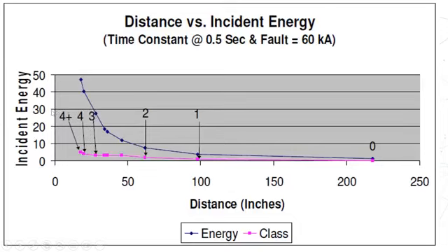Without knowing the incident energy which they are going to receive now at the working distance of 24 inches, approximately 30 cal per centimeter square, as opposed to if the working distance was maintained at 36 inches, the incident energy was 10 cal per centimeter square. So the PPE which he was wearing for the same job at 36 inches won't be able to save him if any arc flash event occurs. So this is the importance of the working distance.